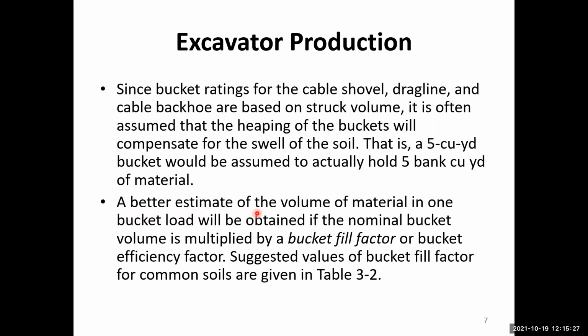A better estimate of the volume of material in one bucket load will be obtained if the nominal bucket volume is multiplied by a bucket fill factor or bucket efficiency factor. Although of course we can use the earlier assumption, a better estimate can be obtained by using a parameter called the bucket fill factor. The suggested values of the bucket fill factor for common soils are given in the next table.